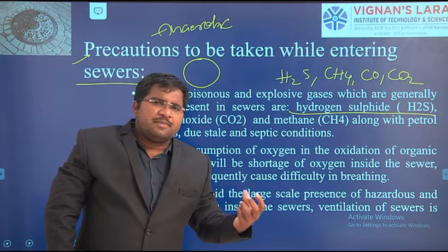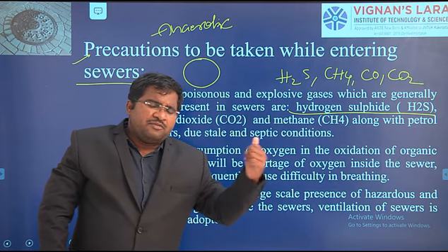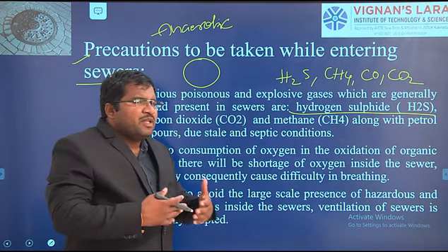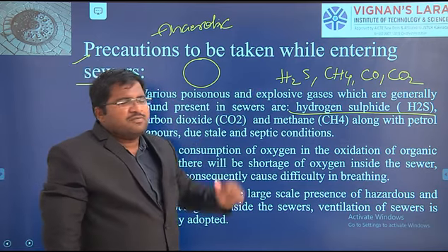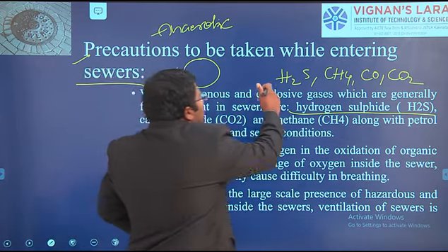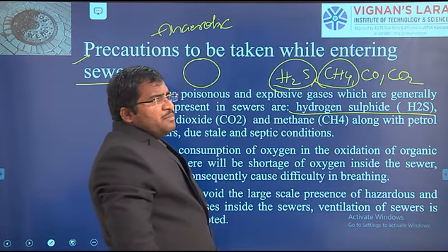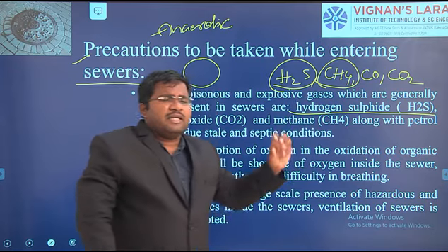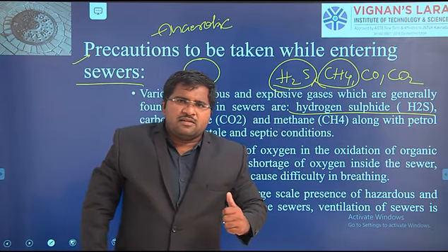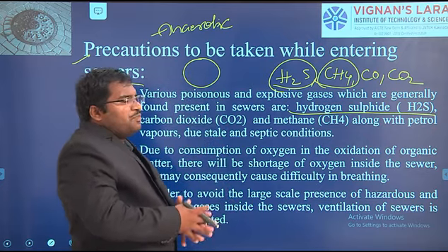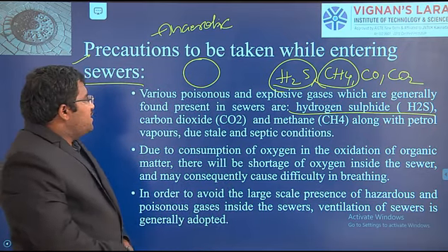Even if wastewater is beside you, you can feel that smell. So why is that smell coming? There is bacterial activity. If that happens under anaerobic conditions, these types of gases will come. Here H2S is a more poisonous gas and methane is a more explosive gas. Because of these two, the laborers can die, so we have to take proper precautions while entering the sewer lines.